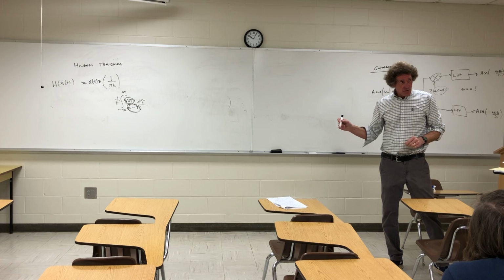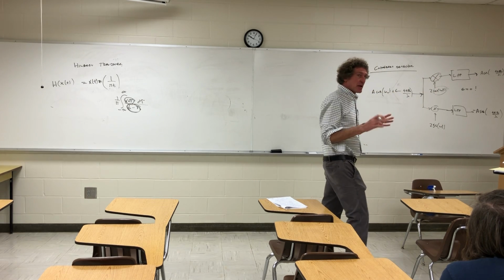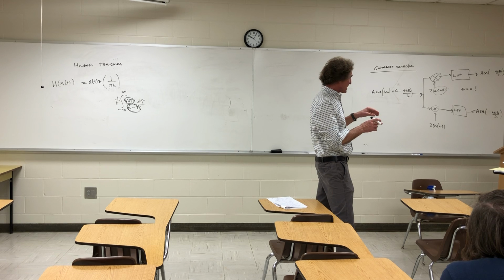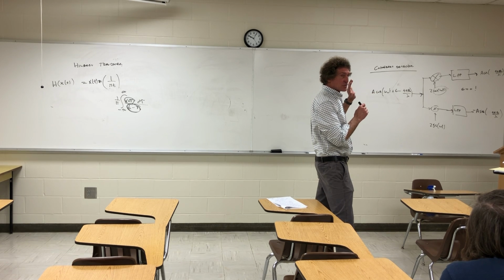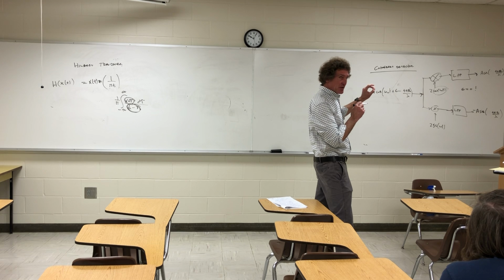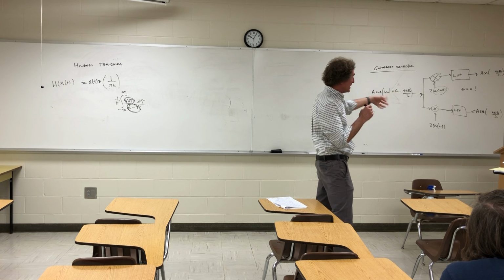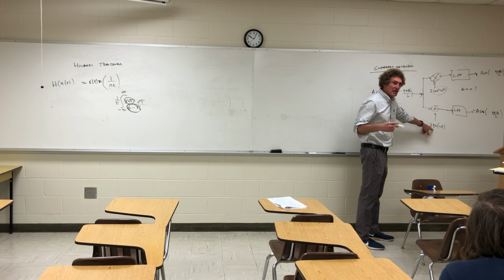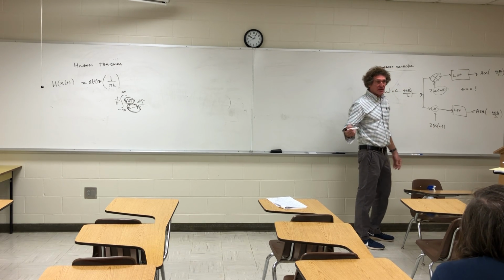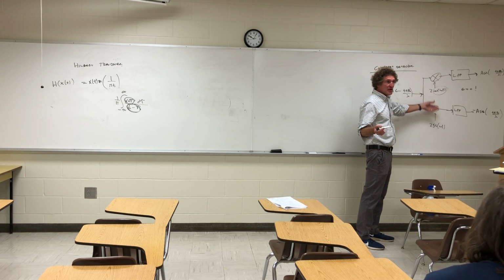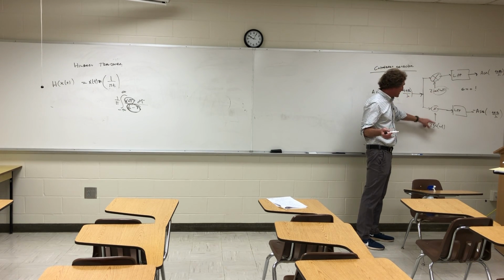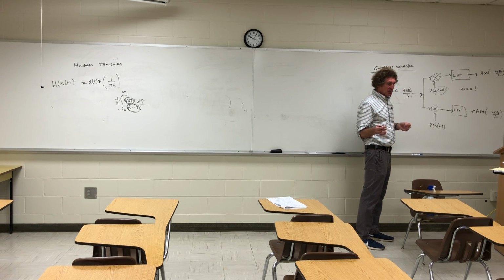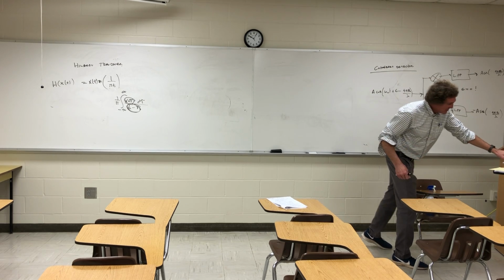Does it change it by a lot? Let me level with you, all right? I have not done any kind of studies where I've taken a look at the actual total effect, but I know this much. From everything I've done, when they're talking about how stable a local oscillator has to be, and for this phase change, does it have to be exactly 90 degrees difference, or can it be like 89.999? The percentage error in here is like 1 millionth. They're talking about parts per million difference in the total frequency of these two with the exact 90 degrees phase change. And there's a lot written on this. I've got a paper right here.